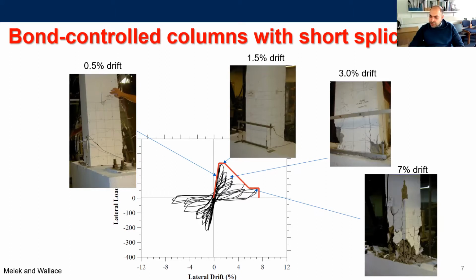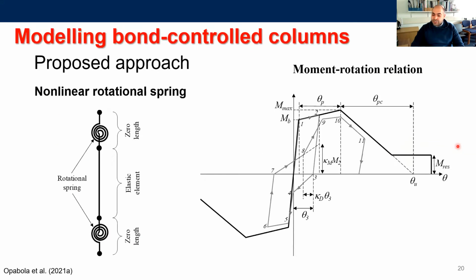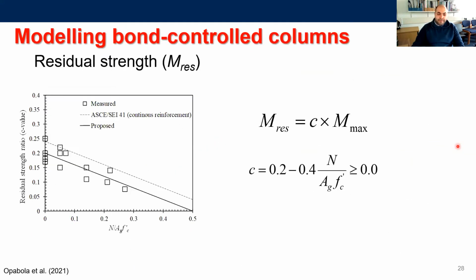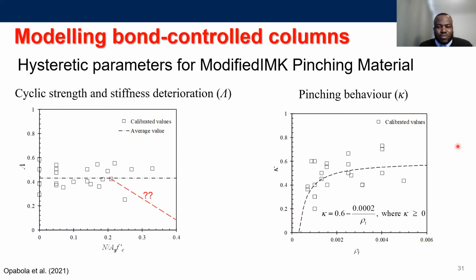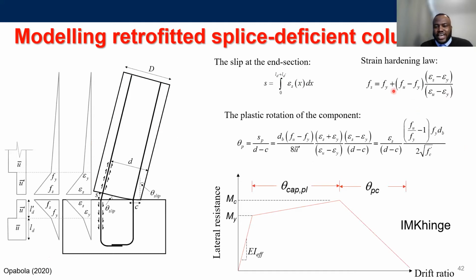Yes, I have a question regarding nonlinear modeling. If we apply FRP for a column and we want to use a lumped plasticity model, which plastic hinge length model can we use? Yeah. So let me go back to the slide where I showed the relationship. Although I don't go into details, if you check the paper, there is already a plastic hinge model incorporated into this formulation. And that is how the model calculates the required length to transfer that particular strain.